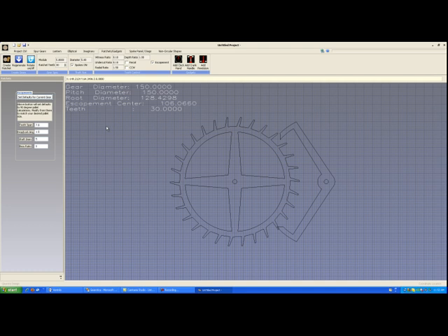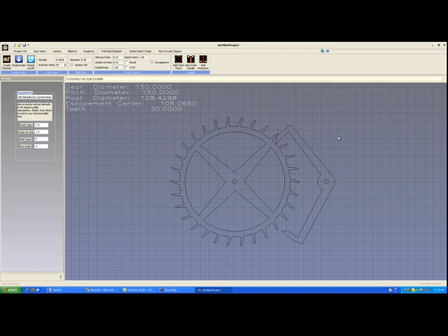When you first generate your escapement, you may see a bit of overlap or cut in, such as the tooth on the bottom here. Until you press rotate, you really can't judge because the angles have not been synchronized between the pawl and the deadbeat. That having been said, let's take a look at an escapement so that we have an understanding of some of its nomenclature.